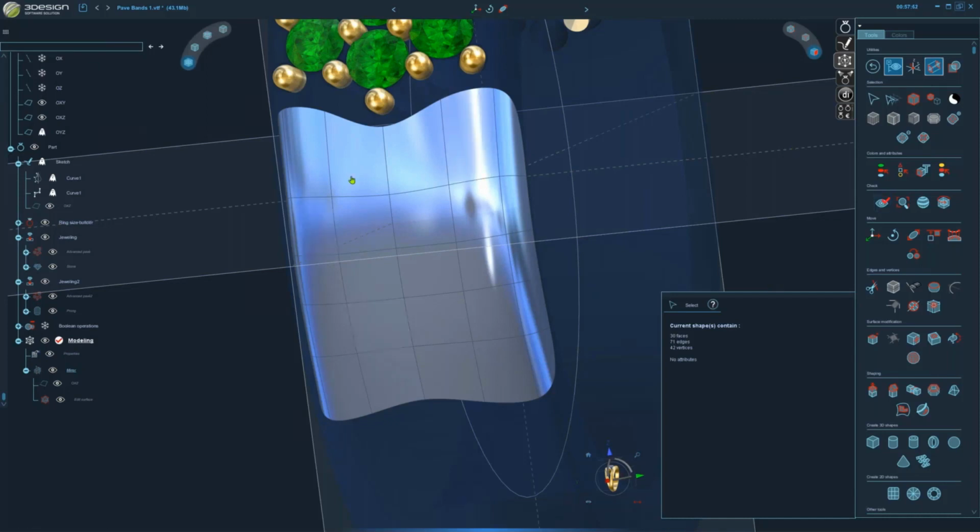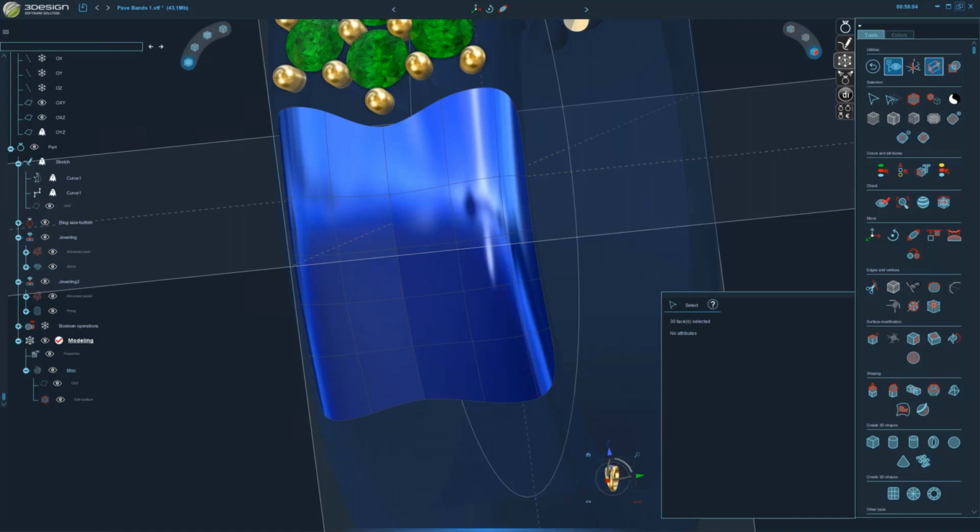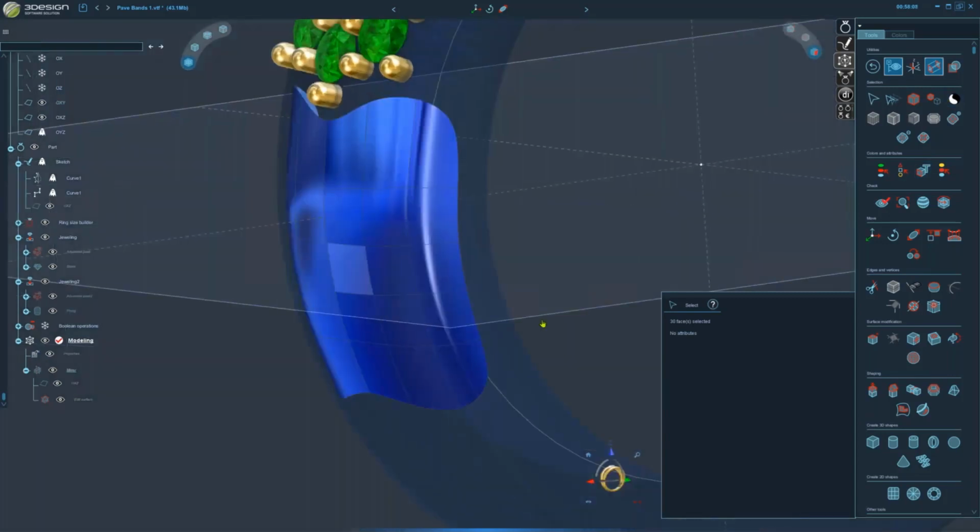Okay, so now that we've added this new edit surface, you can see it's back to being one full mesh. This is after the mirror has taken place, and it's a completely new edit surface version of the whole mesh. So I'm going to double click here and select all. You can do that up here in the menu as well, but double click is the shortcut. Select that entire surface, and we want to give this thickness.